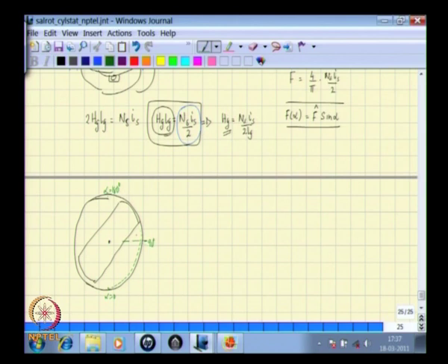In order to find out how much of this MMF acts along the rotor which has a small air gap area and that part which has a large air gap length, we resolve this MMF into two parts, one which is always acting along the rotor axis, that means one which always acts along this axis, and another which always acts along this axis.